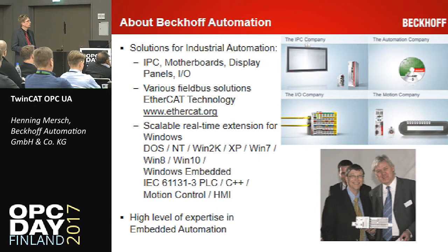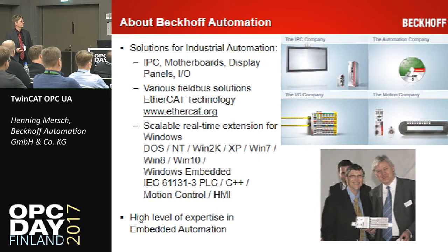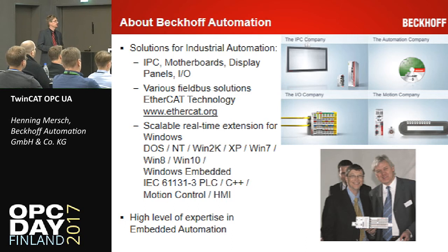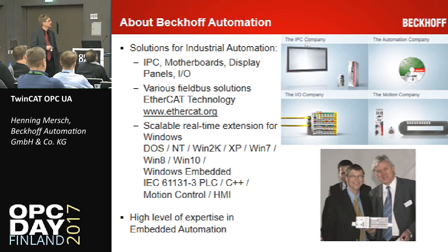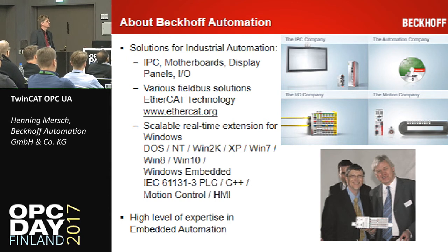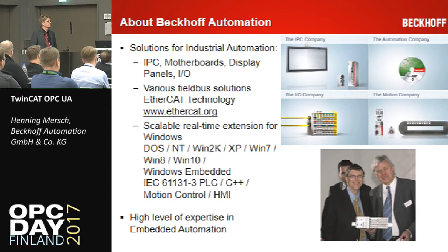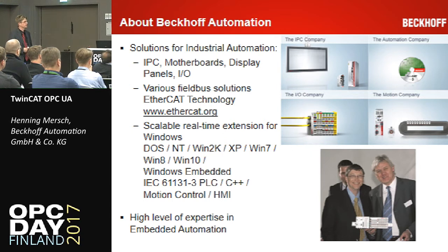All our controllers, and that's one of the foundations for the OPC UA implementation, are founded on Microsoft operating systems, so back to DOS and Windows NT, and now of course we have Windows 10 controllers equipped with our real-time software PLC, the TwinCAT system, which provides you with a PLC and C++ interface in real time.